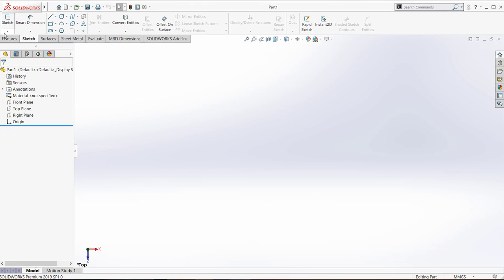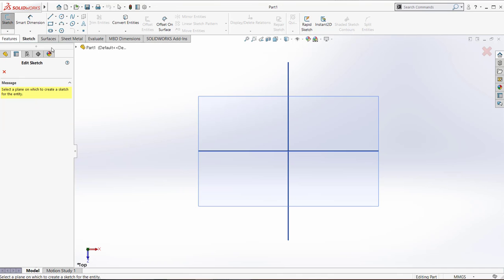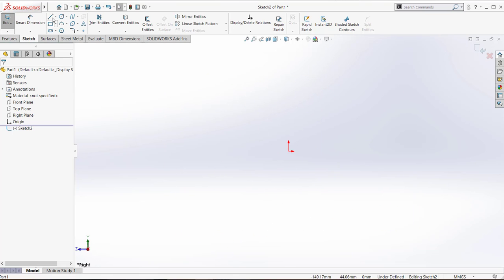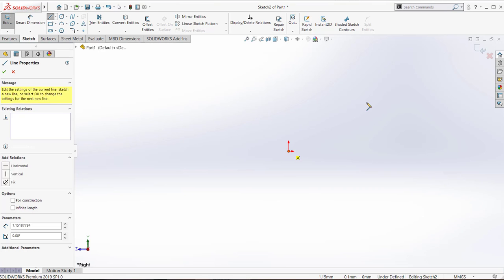Now if we click here, we can see that we have either a sketch or 2D sketch, or a 3D sketch. To click on a 2D sketch, we will need a plane to begin with, so let's select this one for now and start with the very first thing that we have, line. When we hover over somewhere, it would try to create this yellow ribbon. It shows that it's horizontal, and when it's vertical it shows that it's vertical.